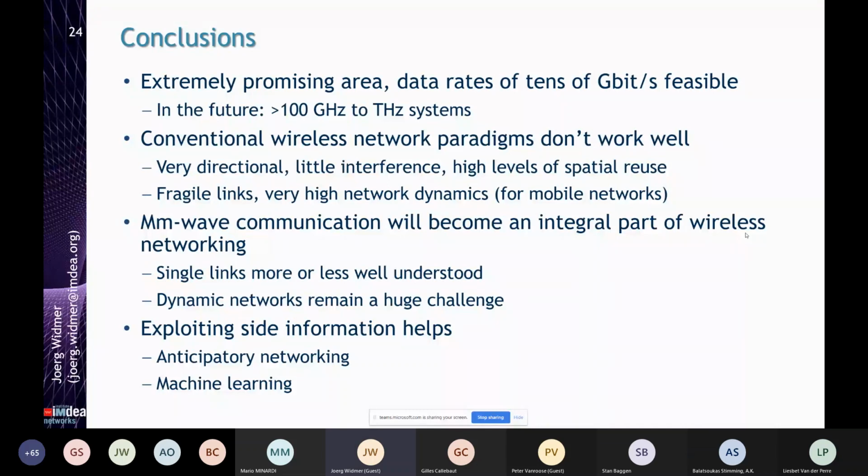And this goes back to then context information helps, right? For example, if you've got a mobile terminal with a gyro and a magnetometer and accelerometer, you can estimate how a user moved the terminal. And then you can counteract that. If the user moves the terminal 20 degrees to the right, then as a starting point, you can try to move the antenna beam 20 degrees to the left in the hope that this maintains a reasonably good link, right?